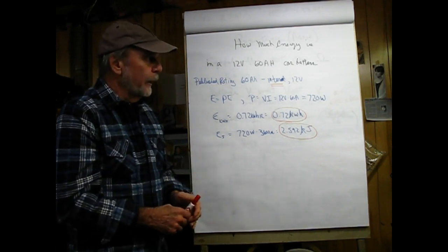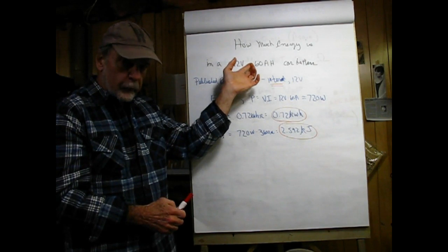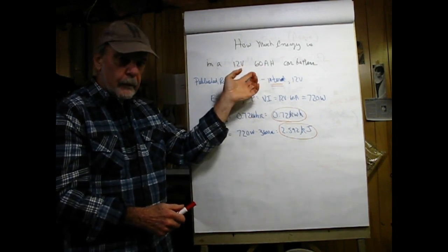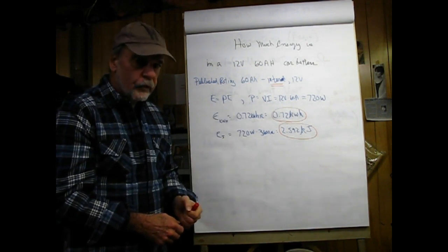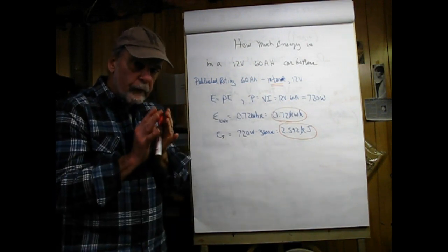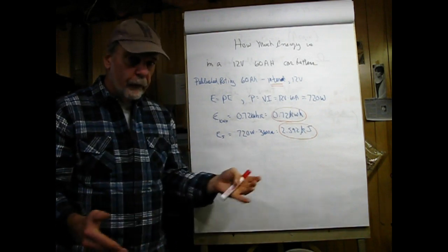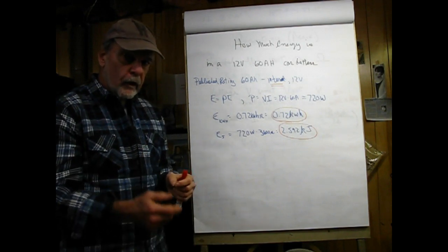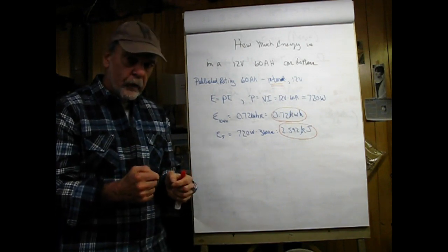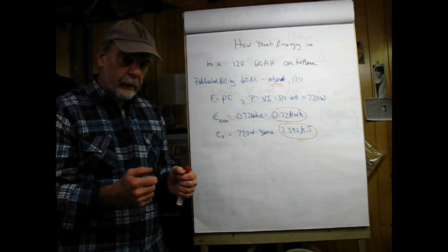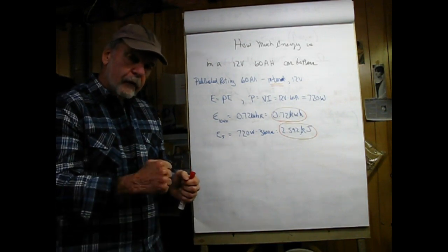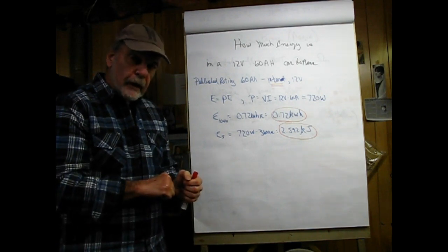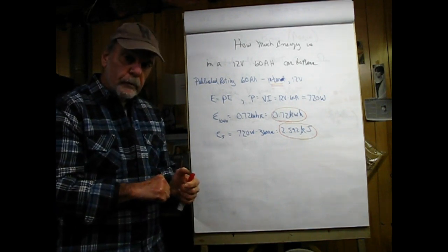Now this battery is rated at 60 ampere hours, but in a short circuit condition this can be 1,000 amperes. And that can produce an awful lot of heat in a very, very short period of time, which is very dangerous. So when you're working on car batteries, always take off the grounded terminal first, which in cars is the negative battery terminal. Reason? You're taking the nut off, and that open-end wrench, say, hits the frame of the car, nothing happens because they're at the same voltage.